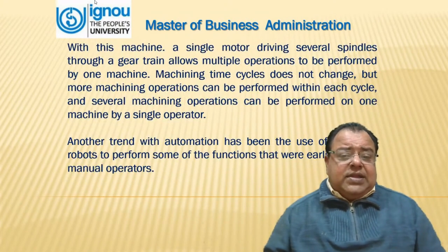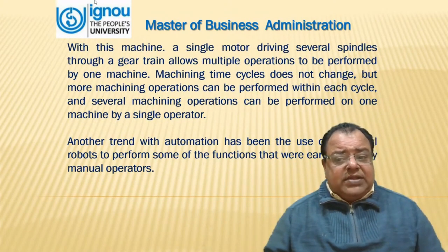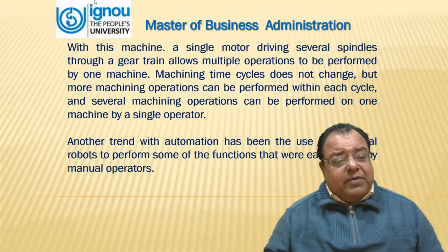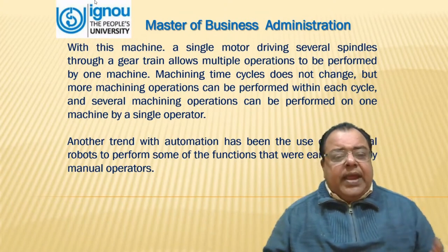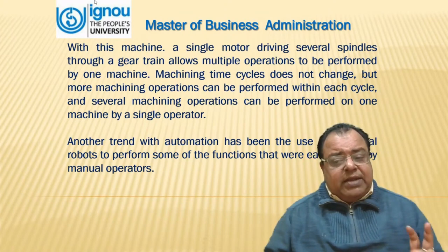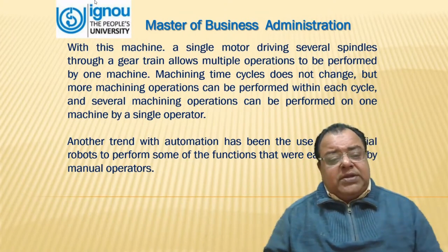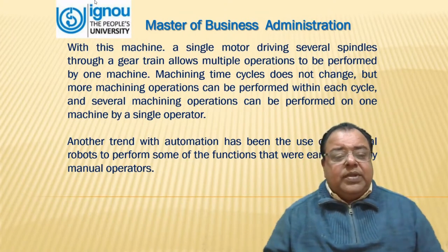With this machine, a single motor driving several spindles through a gear train allows multiple operations to be performed by one machine. Machining cycle time does not change, but more machining operations can be performed within each cycle, and several machining operations can be performed on one machine by a single operator.